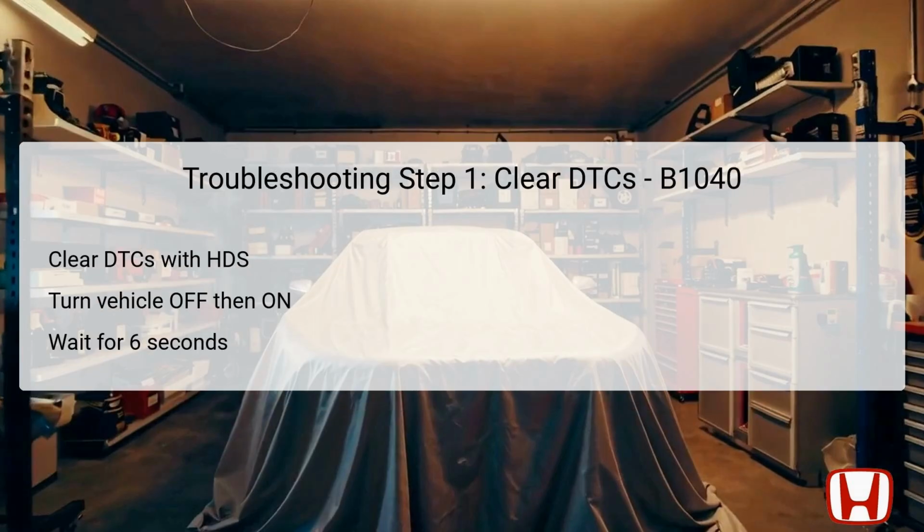The first step in troubleshooting DTC B1040 involves clearing the trouble codes using the Honda Diagnostic System, HDS, a crucial tool for diagnosing Honda vehicles. After clearing the DTCs, turn the vehicle to the off, lock mode, followed by switching it back to the on mode.